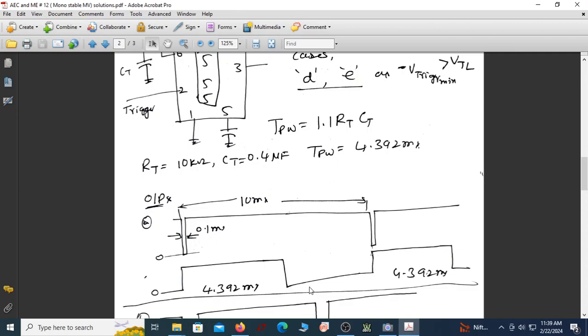Of course, this has to be flat. So this is again 0. It goes to the high, quasi-stable state again. It remains in the quasi-stable state for this duration, because your trigger signal has gone low here and this is high. This will no more extend the trigger signal.